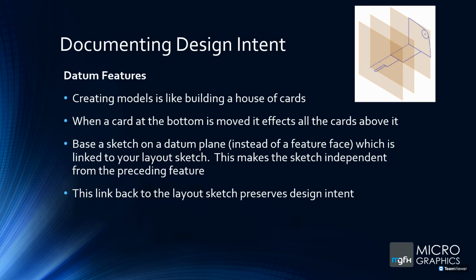Just to reiterate, it's like building a house of cards. If one card at the bottom goes down, everything's going to collapse. Or if it moves slightly, or gets modified, it's going to affect things that are sitting on it. So base the sketch on a datum plane and link it to the bottom layout sketch, and this preserves your design intent. It's what we call skeleton modeling. Everything relates back to one source of truth, which is quite nice when we are working.